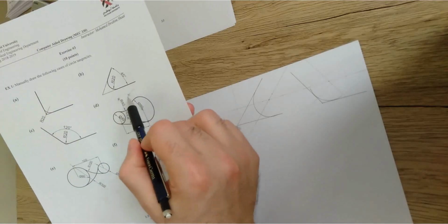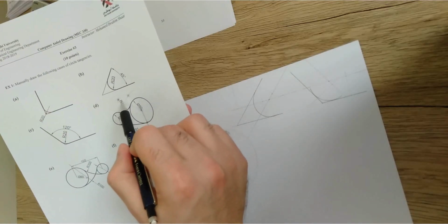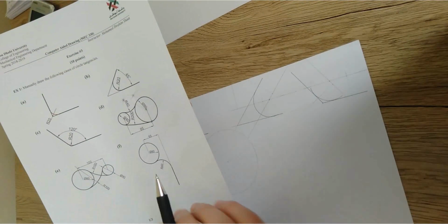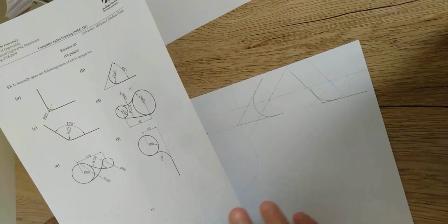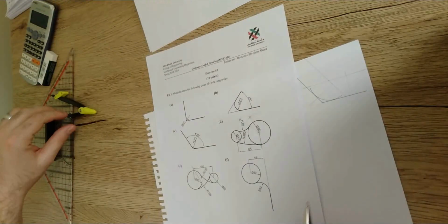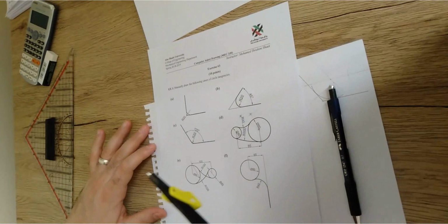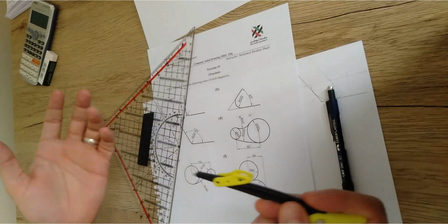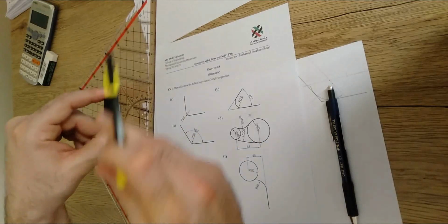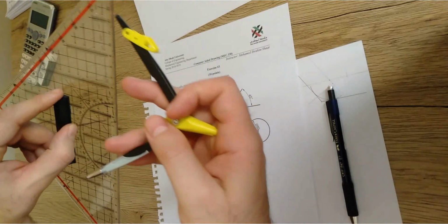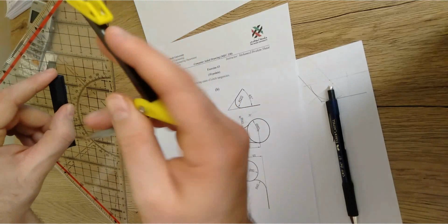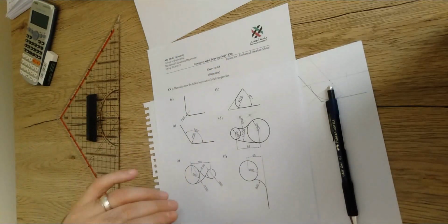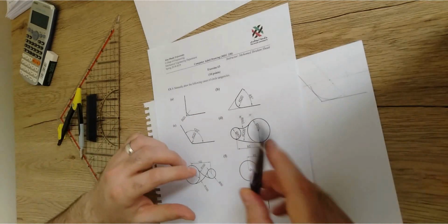The intersection of these two curves should give us the center point of the curve. Then we're gonna open the canvas by the 300. Then we can draw the curve that will be definitely tangent to both of them. Make sense? But I don't believe that the canvas that we have can be opened by 300 millimeter, because 300 millimeter should be almost that width, right? Because this one is exactly 300 millimeter. It is huge. It means that my canvas is too small to be opened by the 300. So I'm gonna do some changes to this exercise here, so you can even work on it at home.